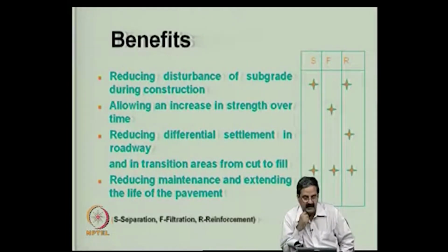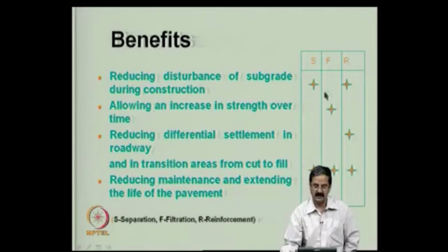And another thing that we have is that the disturbance of the subgrade during construction is less, and that is in fact supported by the separation as well as the reinforcement function. Allowance for increase of strength over time, yes, filtration, because it enables the drainage effect.